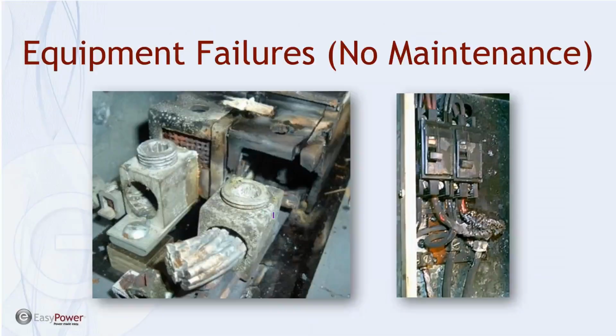Another thing to think about is torquing. Every electrical connection should be torqued. Every electrician should have a torquing screwdriver and a torque wrench, and every connection when it's made should be torqued. Most of the time, what happens is they over torque them, and once they're over torqued, it's just as bad as under torquing, and it's going to cause friction from that compression of the strands, and it's going to cause heat from that increased impedance.